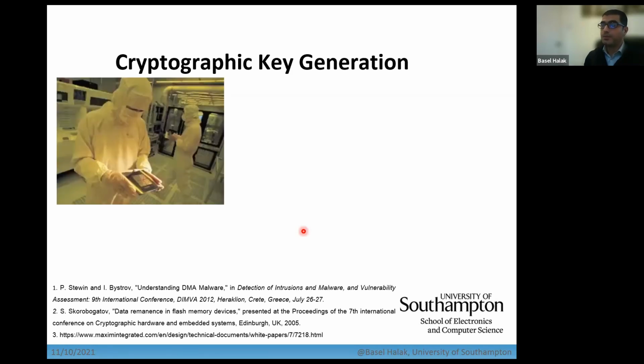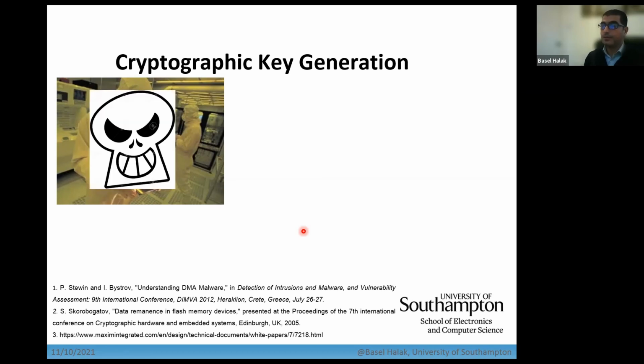The root key should be inserted or stored in a non-volatile memory. The way this is done is either by the manufacturer of the chip or by a trusted party. Now, the problem is we can't always trust those parties to actually inject those keys. So there's too much risk in certain applications. Therefore, we need a better way to mitigate the risk of a malicious trusted third party leaking those keys or using them to undermine the security of the device.